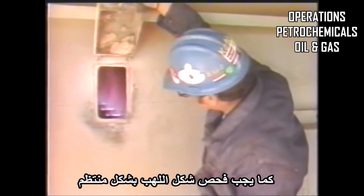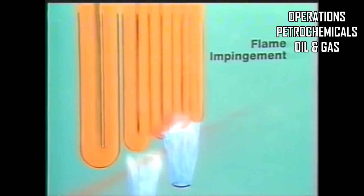Flame pattern should also be inspected on a regular basis. The flame should be bright and clean with no trace of smoke. A properly burning gas flame is blue and compact, while an oil flame tends to be bright yellow. Flame should not touch the tubes. This is called flame impingement. Flame impingement can quickly damage a tube and cause it to rupture. The fire should always be kept as uniform in length and size as possible.